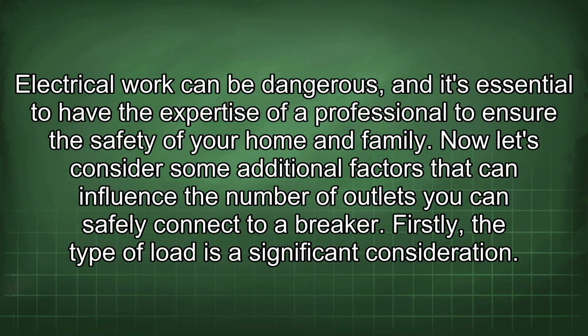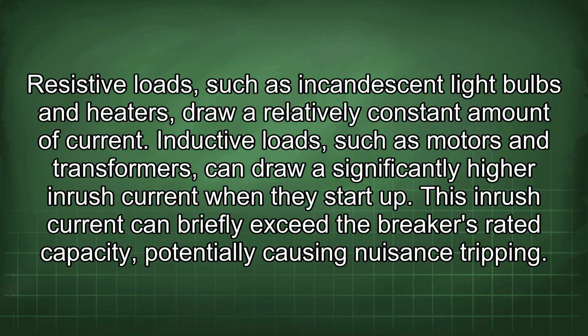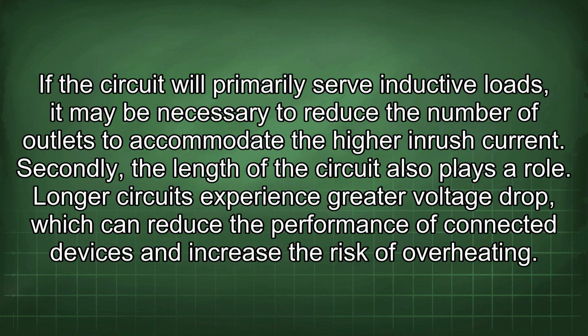Now let's consider some additional factors that can influence the number of outlets you can safely connect to a breaker. Firstly, the type of load is a significant consideration. Resistive loads, such as incandescent light bulbs and heaters, draw a relatively constant amount of current. Inductive loads, such as motors and transformers, can draw a significantly higher inrush current when they start up. This inrush current can briefly exceed the breaker's rated capacity, potentially causing nuisance tripping. If the circuit will primarily serve inductive loads, it may be necessary to reduce the number of outlets to accommodate the higher inrush current.